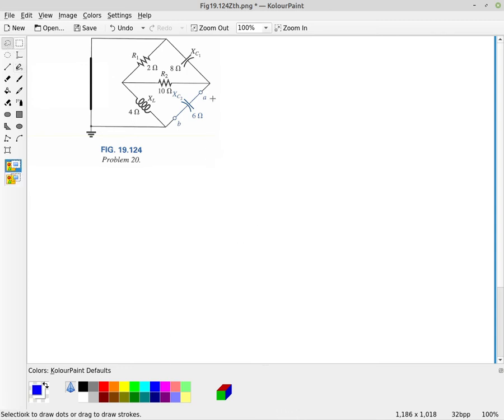Alright, so again, we're looking for the impedance at these two terminals. We do that by shorting out all voltage supplies, opening all current supplies, and then just calculating the impedance. So as we did before, we need to redraw this. I called this A. So this was A before, but now this is all shorted. So now this is all node A.